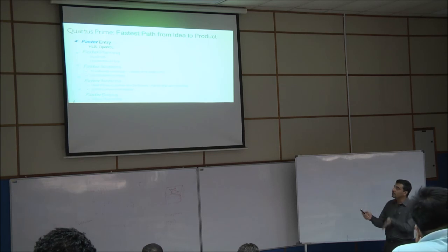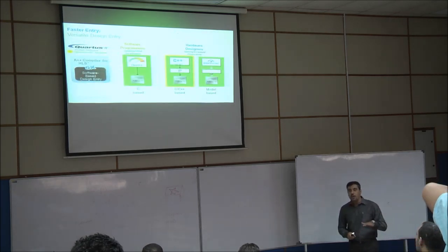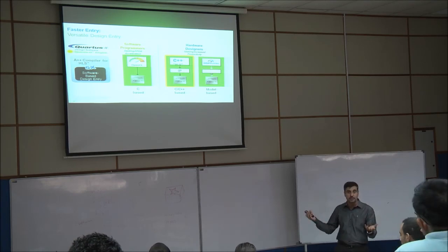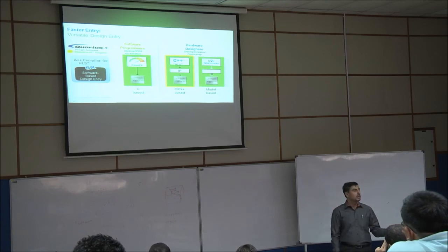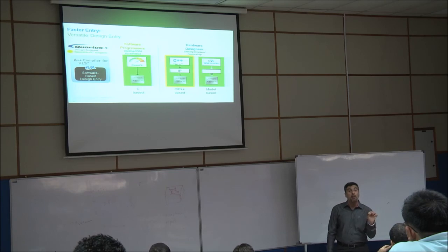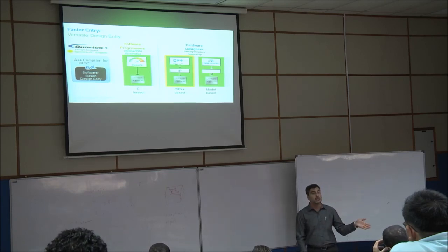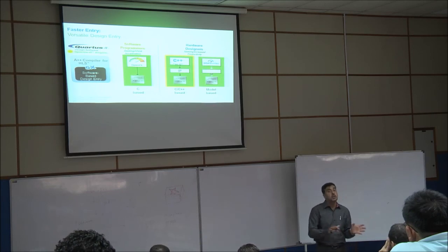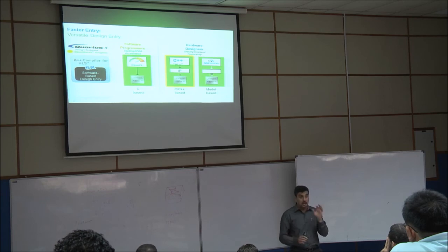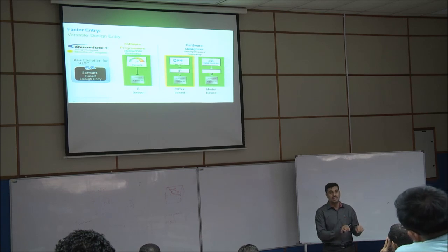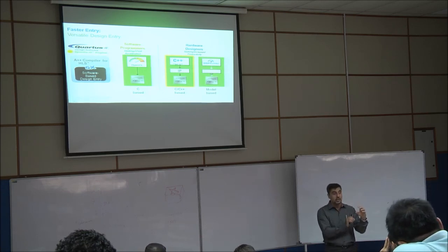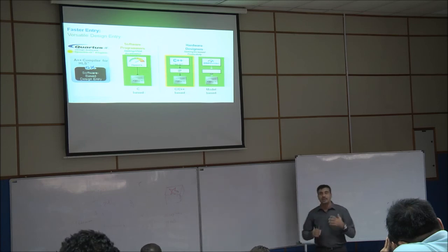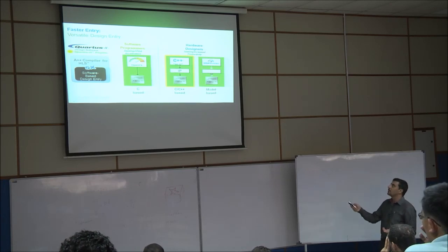I'm just going quickly. Now, for those who are very weak or don't want to use HDL, who are happy with C++, Altera or FPGA vendors give you a platform to use it, by using an embedded core, either soft or hard core, like ARM as a hard core or NIOS or MicroBlaze as a soft core. Clear? So if you don't like HDL, either VHDL or Verilog, you can use C or C++. But at the end, you still have to write some VHDL or Verilog, just a little portion of your code in HDL, just a cover for the C++ and C program. But now it is very easy to use this, so we can use C++ and so on.